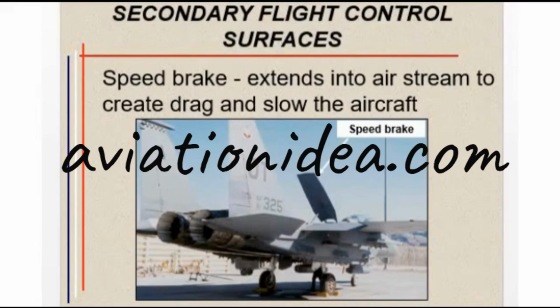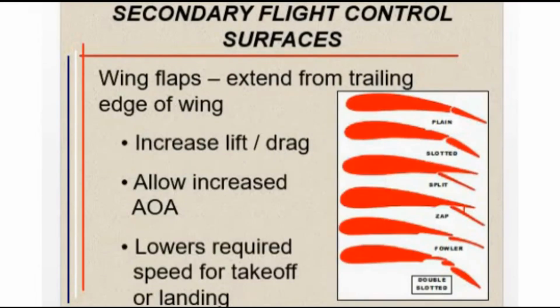Wing flaps of an aircraft. Flaps, Figure 21, are the flat or curved surfaces that extend from the leading or trailing edge of the wing. Flaps are used to reduce the minimum landing speed. They do this by increasing camber and wing area, which lowers the velocity required to keep the aircraft aloft. Flaps also increase drag, allowing a steeper descent into small fields.